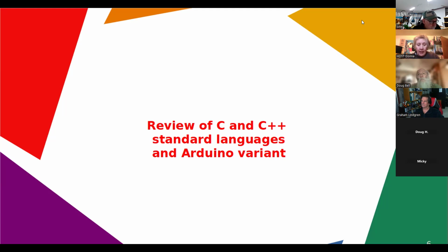Memory access. A key difference between Arduino, or really any embedded system, and the rest of the world is that dynamic memory is really not recommended unless you've got a system where additional RAM chips, external to the processor, are added to your design. For me, anyway, that has been the only realistic way to utilize dynamic memory.